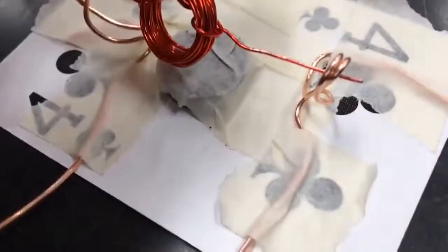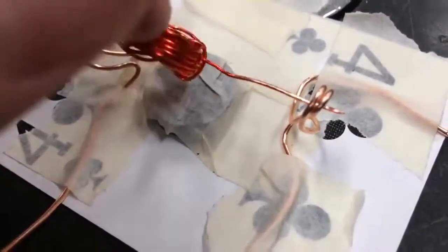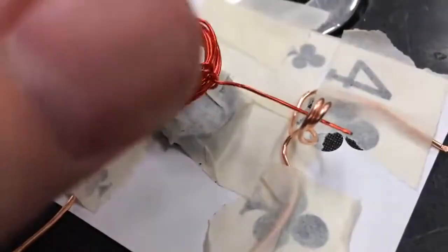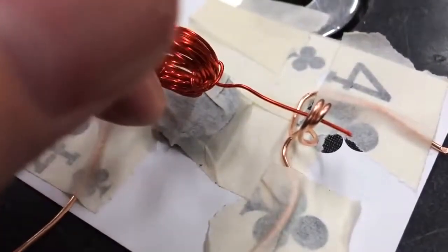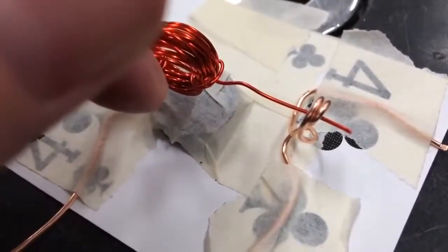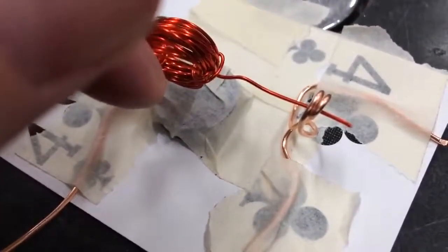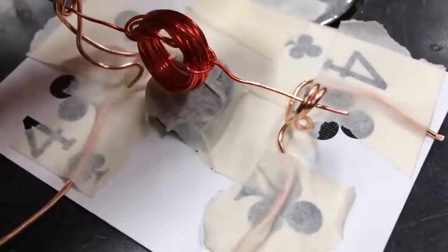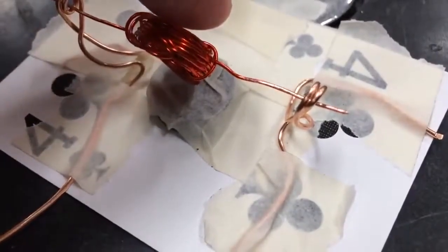Alright, so let's try to solve this problem, and we're going to do it in a way that looks a lot like the brush solution from before, where we control when current gets to certain parts of the rotating loop. If we spin the motor, you can see that half of the enamel's been rubbed away, but the other half is still there. And that means that when the motor's like this, the copper wires are touching and electricity's flowing. But when it's like this, the supports are touching the paint and electricity's not flowing.